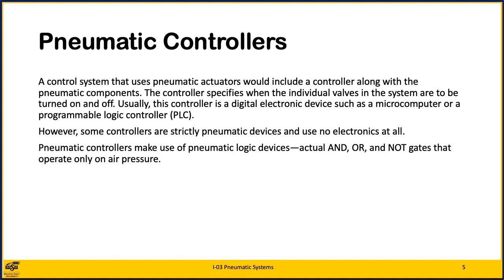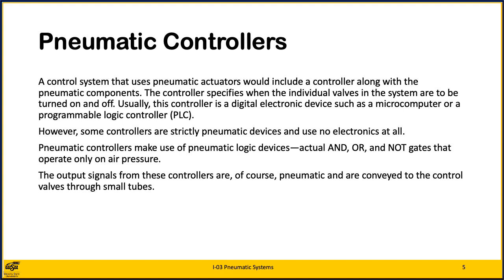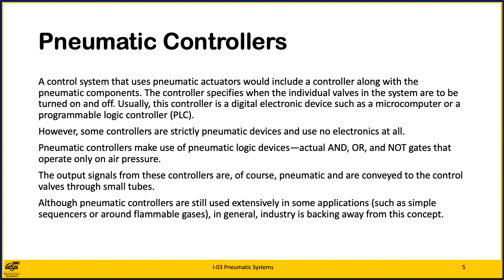Pneumatic controllers make use of pneumatic logic devices, actual AND, OR, and NOT gates that operate only on air pressure. The output signals from these controllers are of course pneumatic and are conveyed to the control valves through small tubes. Although pneumatic controllers are still used extensively in some applications, such as simple sequencers and around flammable gases, in general, industry is backing away from this concept.